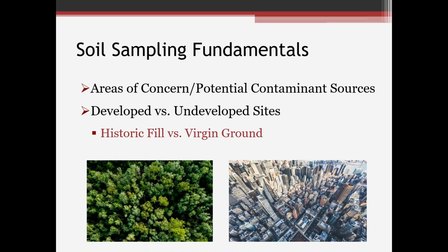Then, you don't want to go into a site blind and just sample wherever, especially if you're getting into larger size properties. You want to have a target for what you're sampling. So identify areas of concern and potential contaminant sources. Then you can get a more focused sampling program going based on that.